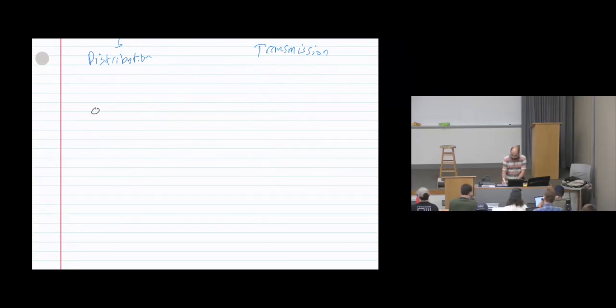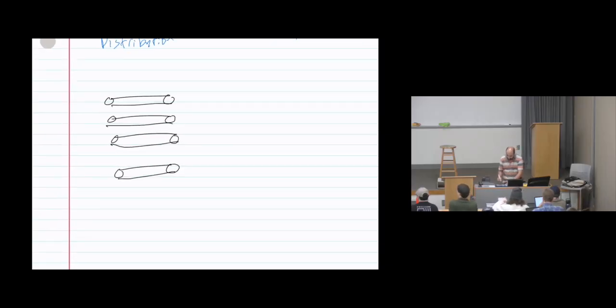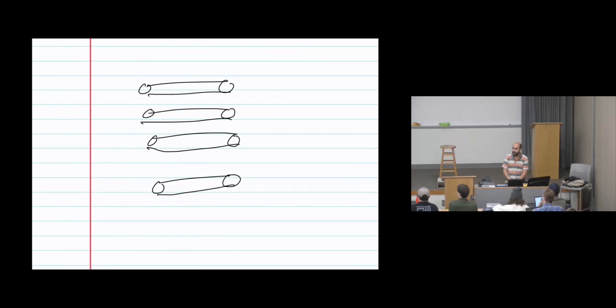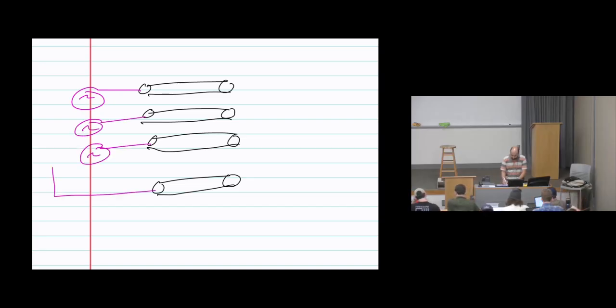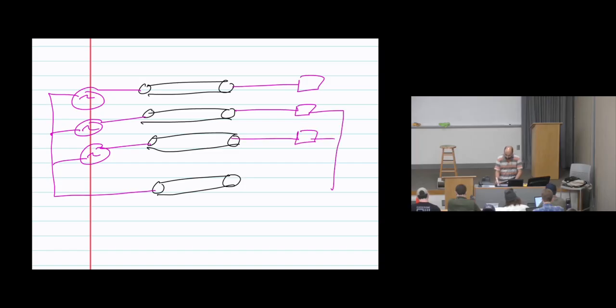So for the sources, again, we have 4 wires, 4 conductors. We can have a source called Y connection. Basically, there will be 3 sources. So here is a voltage source, here is a voltage source, here is a voltage source, and the returning current goes through the neutral. And to the load, we have the same thing, Y, where here's an impedance, impedance, impedance for each phase. This is called Y or star connection.